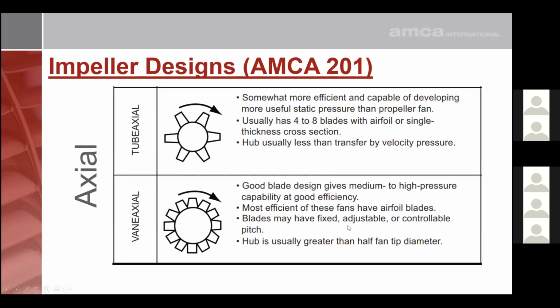Also, some axial fans. We have what we call a tube axial fan, and it can be any kind of impeller blade, but essentially it's an axial fan impeller mounted on a motor or shaft, and the flow exits axially, but has a high rotation component.